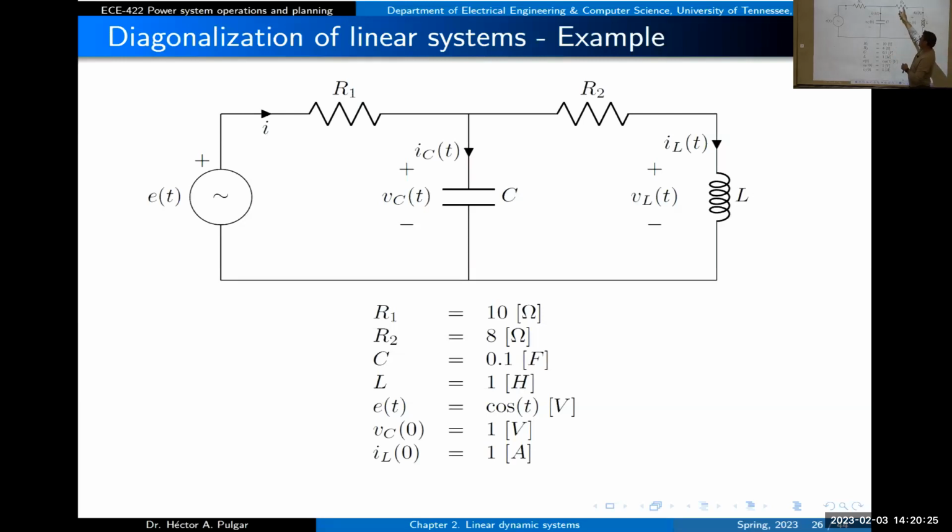If we put this, what will happen? Well, you will have a typical RLC circuit. So this is important to add damping to the system. But now we're putting this other resistor as well. That also will take some energy, mainly from the capacitor. So if the capacitor has a high voltage, because the capacitor is gaining energy, this will start dissipating part of that energy.